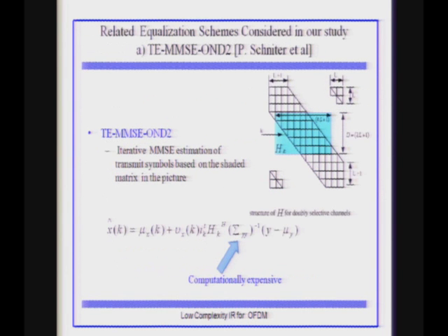So this is a scheme, one of the schemes that we are going to use. I call it the MMSE based turbo iterative scheme with square complexity. It doesn't reveal much, but what does it mean? It has linear complexity, but square in this length. That's what it means. This is a scheme that was proposed from her advisor's group. The estimation is the conditional mean, the standard formula that we saw before.